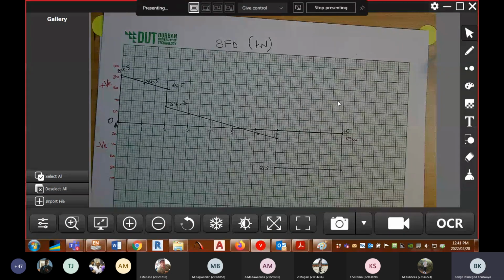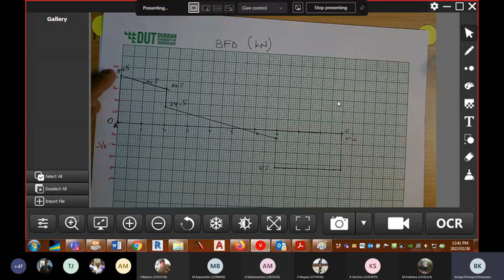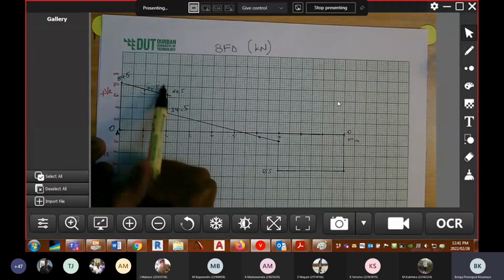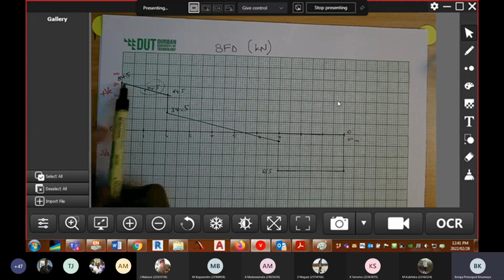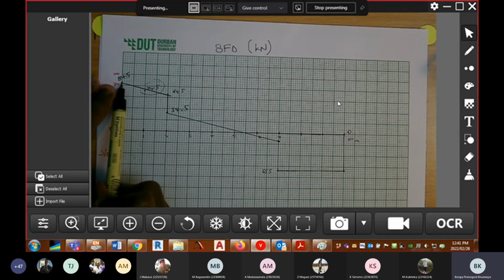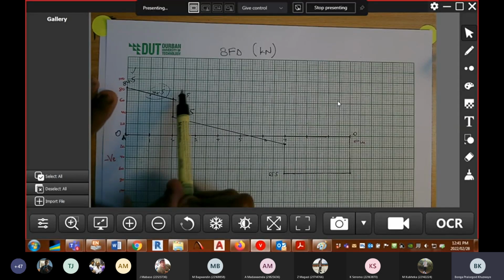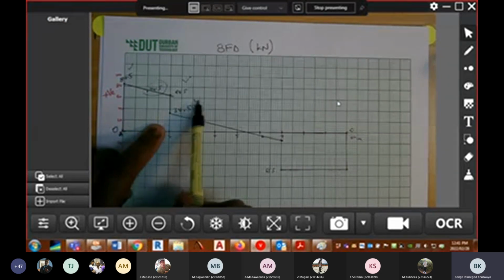if I ask for a fully annotated shear force diagram, you don't really have to show that 74.5. I just did it because at that time we were doing it every meter. So you need to show that 84.5, you get a mark for it. You need to show that 64.5, you get a mark for it, or half mark. 34.5 needs to be shown.